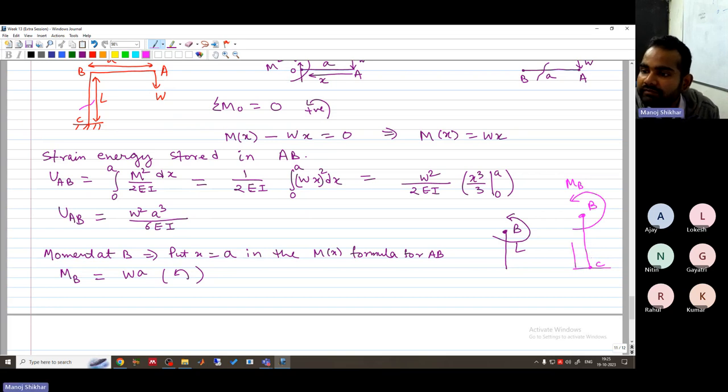This is our positive direction, this is our Y direction, and we have a cut here. This face was the positive face, so the opposite face will be negative, and the moment will be in the clockwise direction. Suppose this point is P. So here we have My, and the load will be in the negative direction. So this will be V.